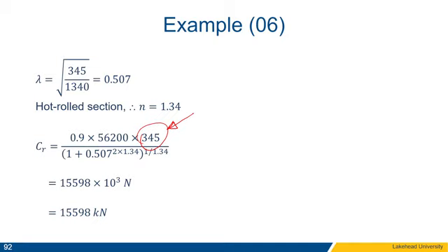First, because the plates are minimal area compared to the I-beam, and also we are going into the conservative side. If you would like to be very accurate in that, you should be doing a weighted average. So you multiply the area of the I-beam by the F yield of the I-beam plus the area of the plates multiplied by the F yield of the plates.